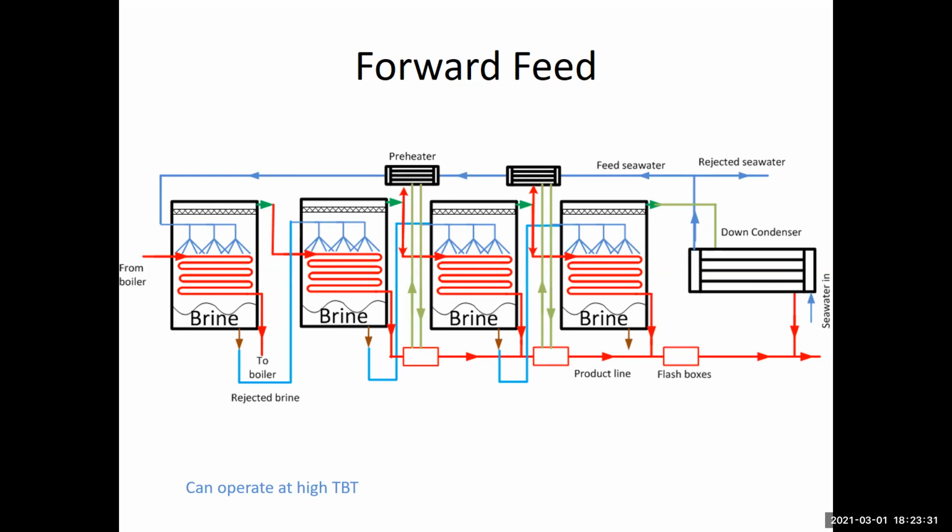You have a fluid, liquid, coming from high pressure into a low pressure. What will happen? Flashing is going to occur, so some vapor will form. You take this vapor up here to help in preheating the feed. It will condense. You collect all the condensate, the part that you took from the formed vapor and the part that you took from the flashed off vapor, and all of it is going to get back here again.